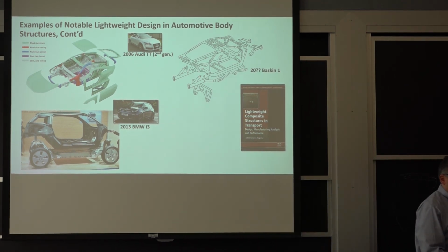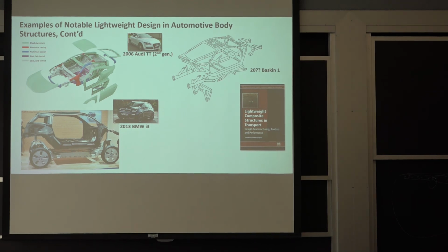So thinking about the two ends of that spectrum, the space frame and the monocoque, understanding that the monocoque might be understressed, understanding that there's technology out there that's been developed for bicycles where you can somewhat inexpensively make carbon fiber bicycle frames, how can you marry those three? How can you find that mid-spectrum structure that takes advantage of the carbon fiber, uses the most efficient load paths, doesn't include extra material?